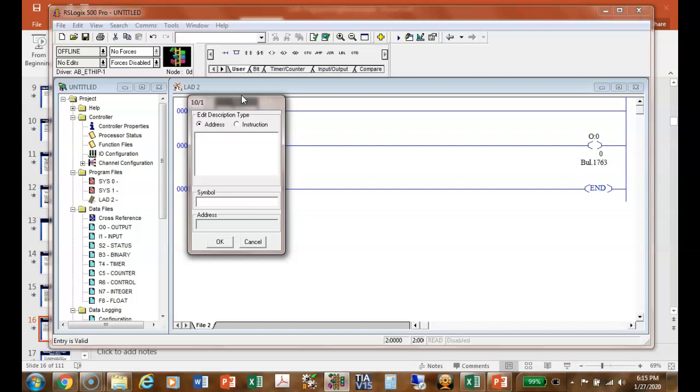So if you ever got into a PLC program where the programmer didn't tell you what each rung did and how things were supposed to work, then that means you got to figure it out by yourself. So you love these guys to use comments. Every PLC language that I've ever programmed in gives you the ability to add comments to a rung.